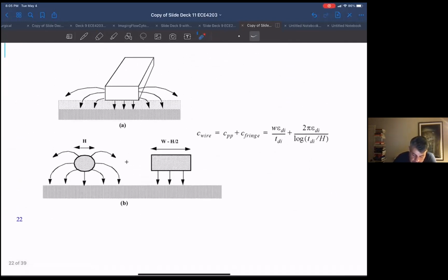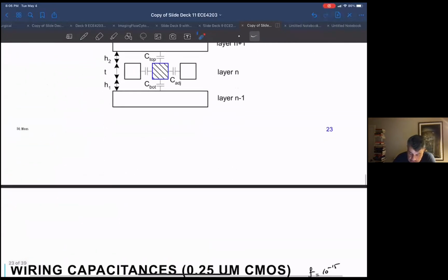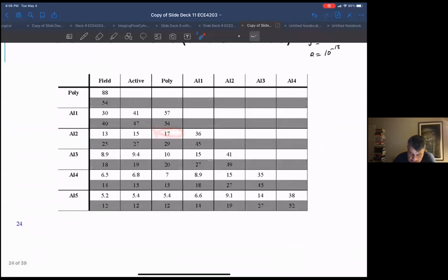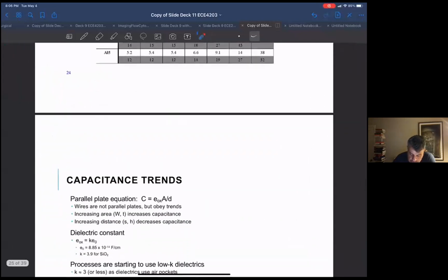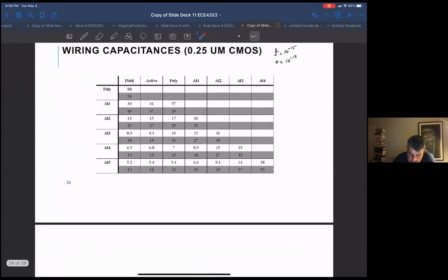capacitance, again, you only have two sides regardless of how wide you are, and this thickness isn't going to change. So you just give this total value per unit length, but then the designer has the option of making this wider, so the parallel plate capacitance can be bigger, and you have to multiply that by your area. So you have to keep track of both of those numbers. And again, this has the weird effect that the fringe capacitance is given per unit linear dimension, or per micron, whereas the parallel plate is given in terms of micron squared.